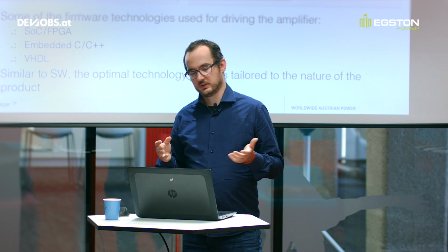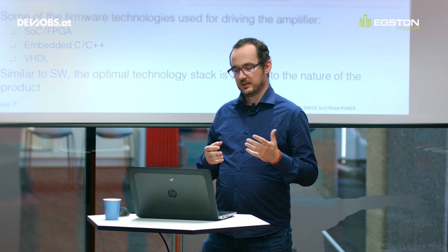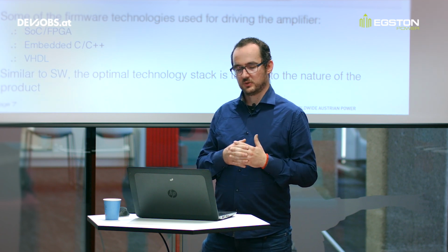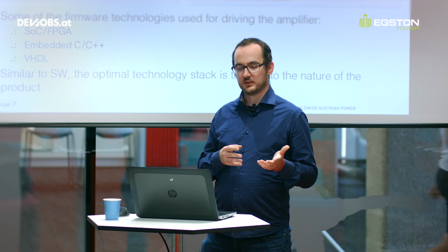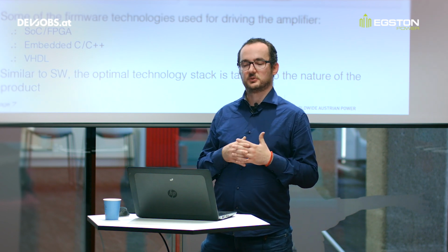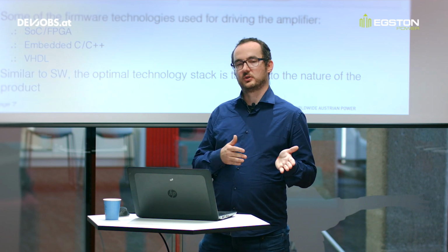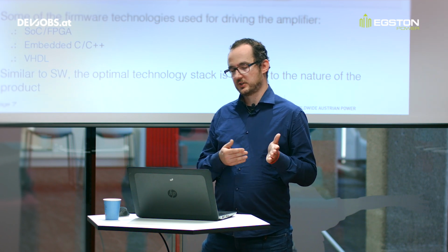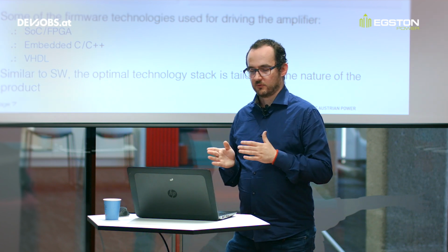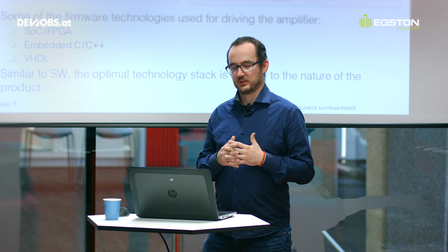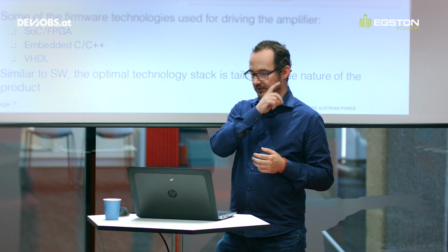In terms of embedded programming, as we already know, on system on chips, there are embedded microcontrollers for which we can use either a bare metal approach or embedded Linux using C or C++ in order to optimize it with some real-time flavors to it, but also non-real-time flavors where we practically need to establish a TCP/IP communication in order for the graphical user interface to interact with it properly, to communicate the status of the system back to the graphical user interface, and so on.